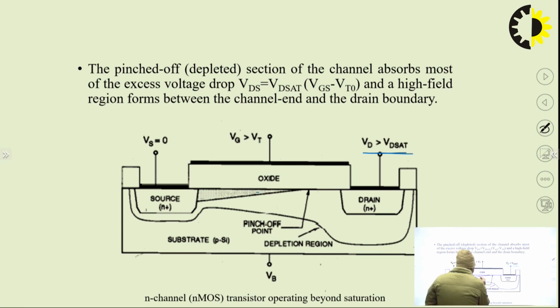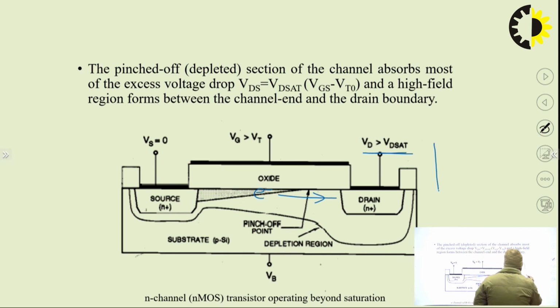Now electrons have high kinetic energy. They have gained velocity beyond the drift limit, and they do not need any conducting path between source and drain. These electrons drift from source to drain, and the value of current will be saturated; it attains its maximum value and is maintained. So we get the characteristic curve like this. The value of current will be saturated.